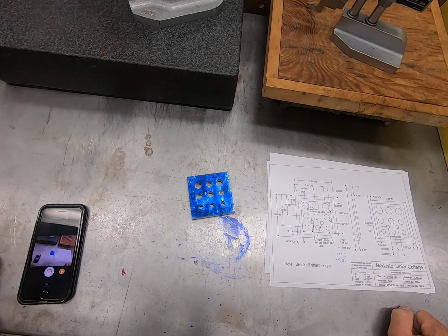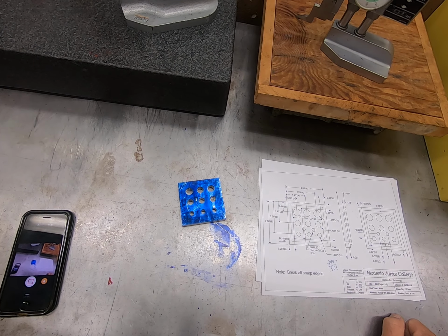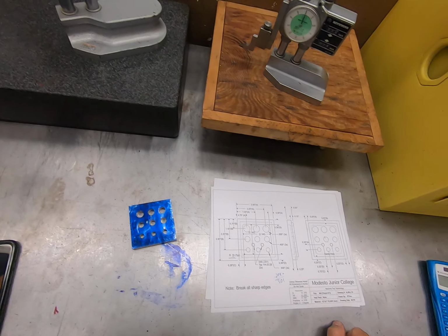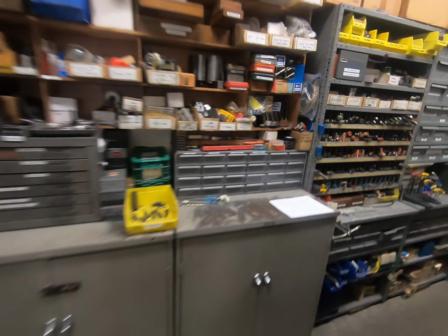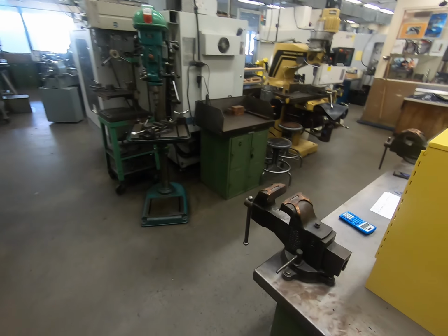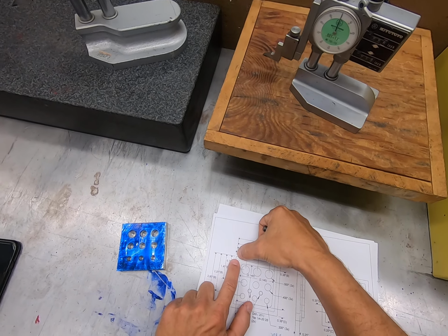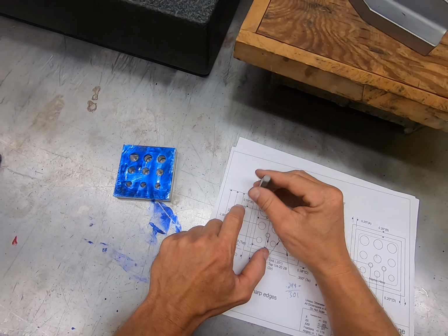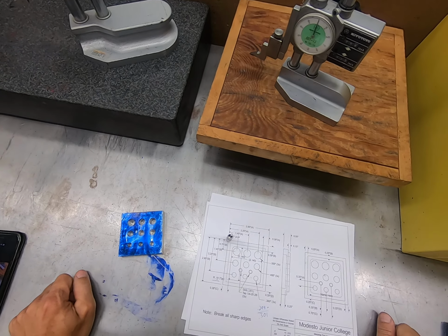There's a few different ways you could create this pocket. You can do it by edge finding and setting exact numbers, but it gets to be really skewed because of... let me give you an example. All right, so here's a 3/8 end mill. If I edge find to this corner like we've been doing previously, what's going to happen is my end mill is going to be sitting, let's go this way, directly on the edge of that corner.